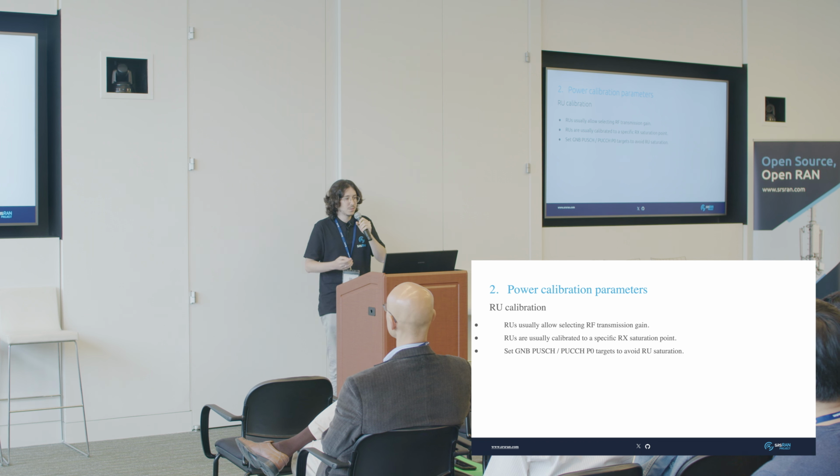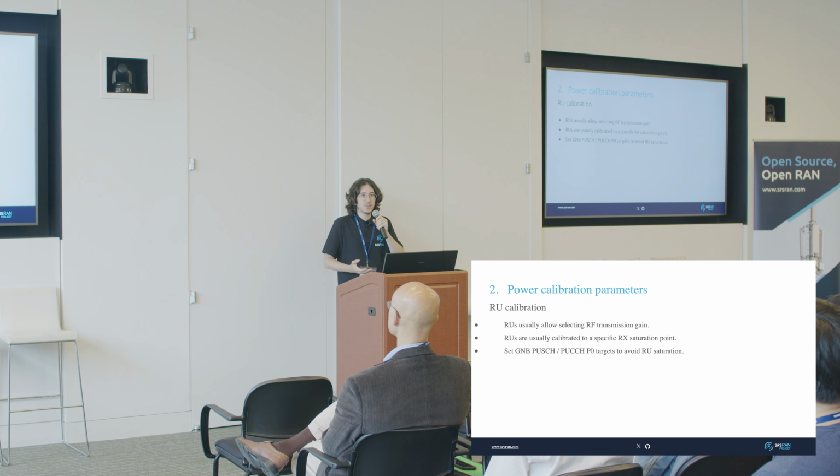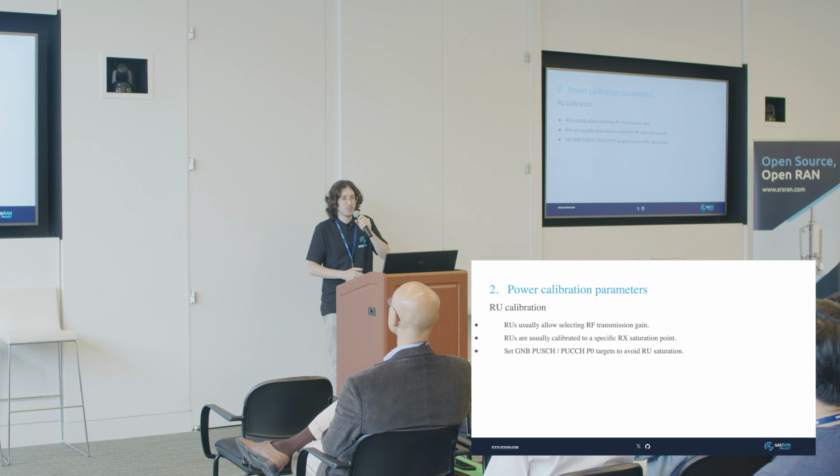Many commercial RUs support tweaking the transmission power of the RU. It is just that it is not possible to do it from the G-Node B configuration, but you can still apply the same procedure that we will talk about just by manually configuring this in the RU.